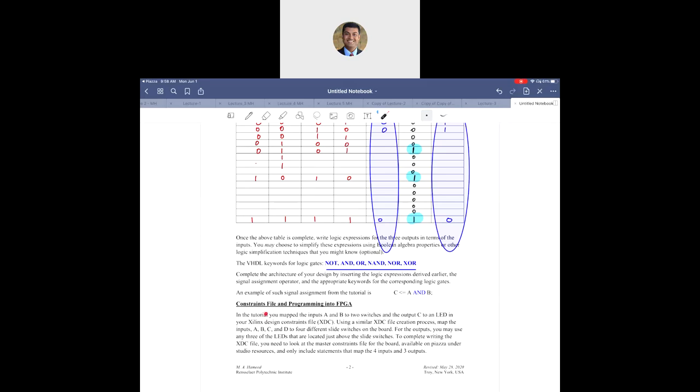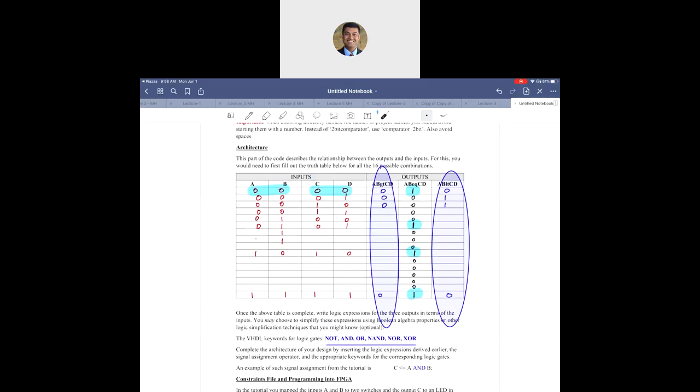You can do a design rule check, the DRC, and then use A, B, and C, D as your switches. And the outputs, you can put them to LEDs. You can map them in your Xilinx design file to LEDs, and then run through all the 16 possibilities and check whether the LEDs are lighting up correctly or not. Now, so that's essentially what the studio is.